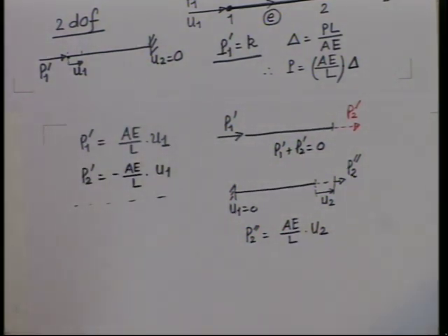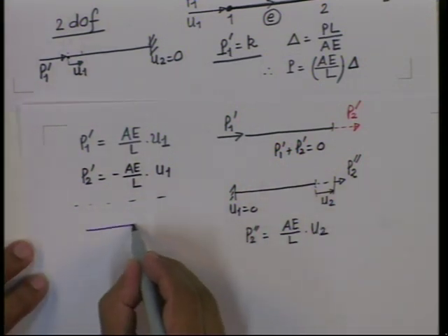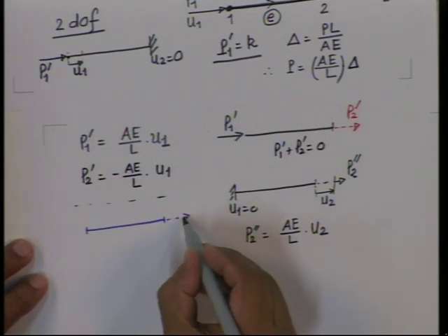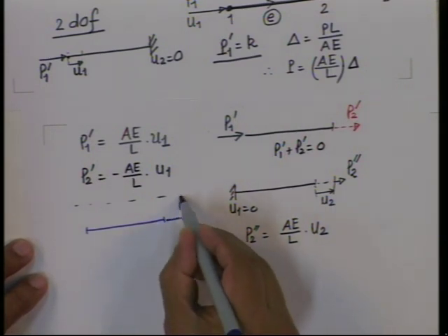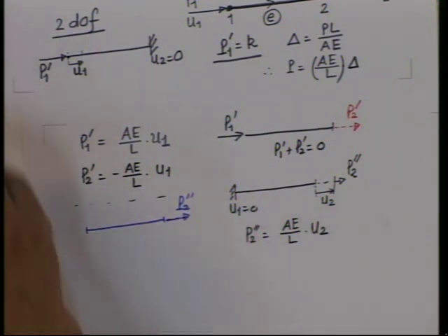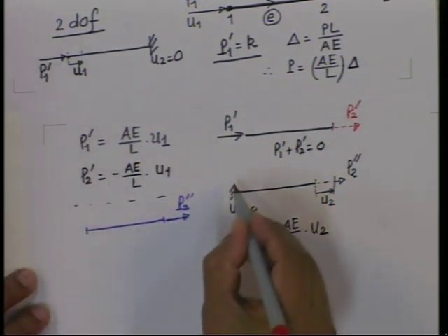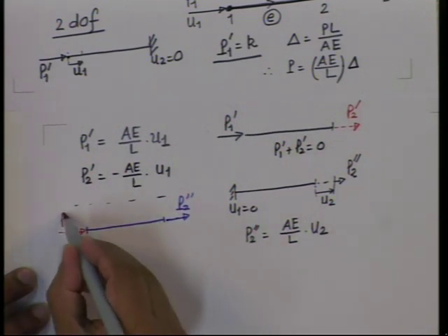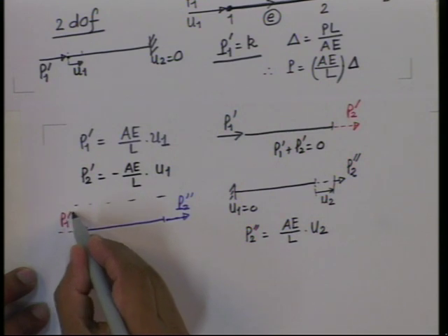Again draw the free body diagram. When we draw a free body diagram, we need not worry about displacement, it is only forces. So you cut it and show the reaction in the same direction.